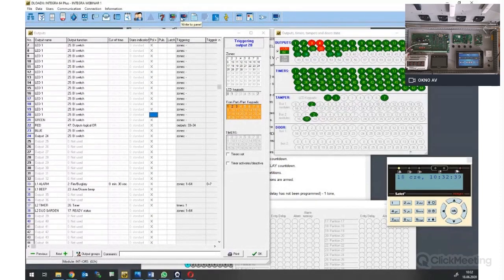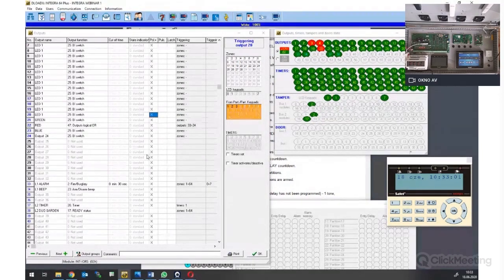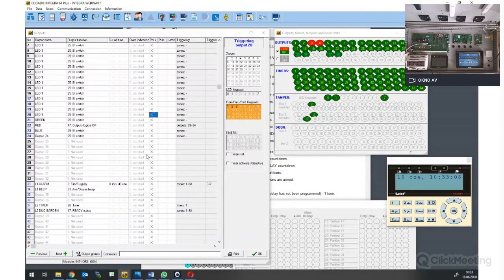There is a difference between normal and triggered status, or active status, and the status of the physical output. In this case, this is negation. So the normal status is giving 12 volts or COM, etc. If I mark this option, then normal status is nothing. No input is sent. I hope you understand this part.